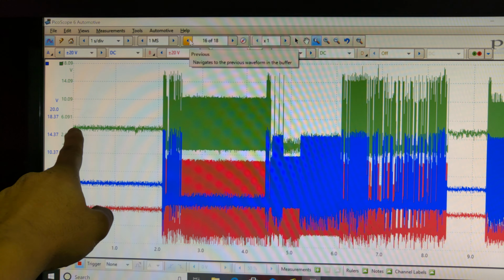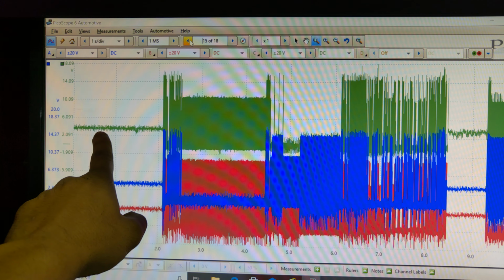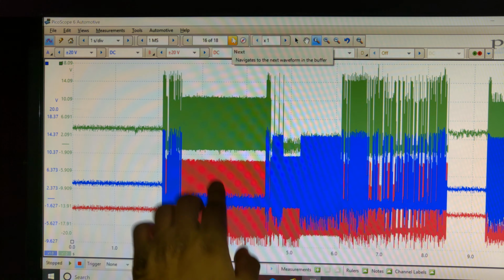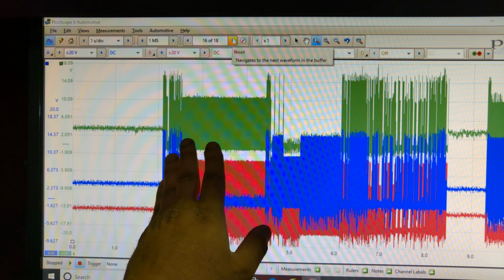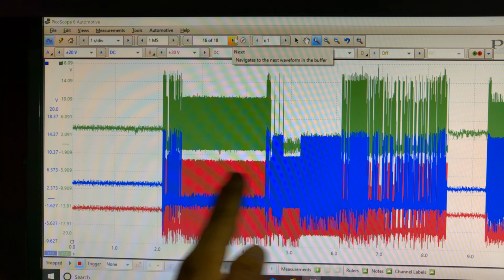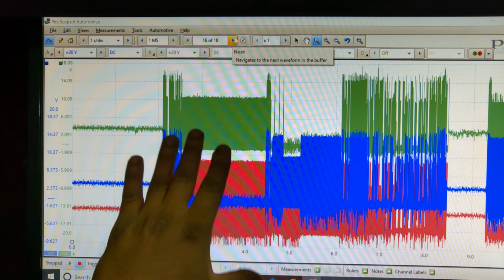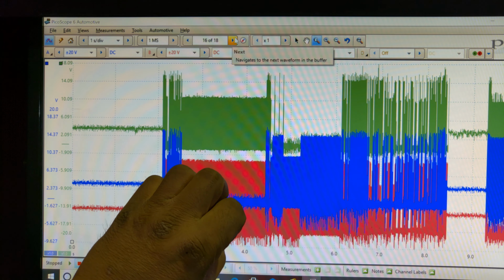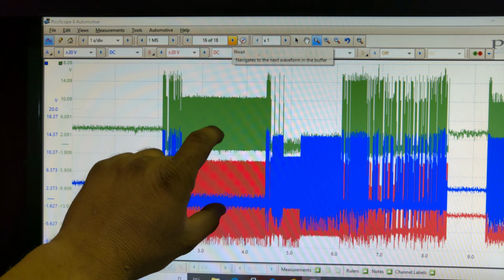Before I say anything, like I said, the car is running up until this point, all the way. So when this went up and down like that, what I did was I went from park to reverse. So that's where the reverse clutch is engaging. I'm thinking this is what the reverse actuator is.